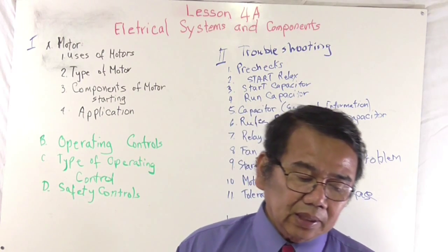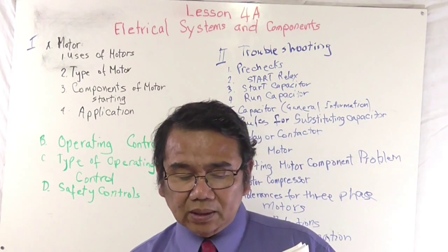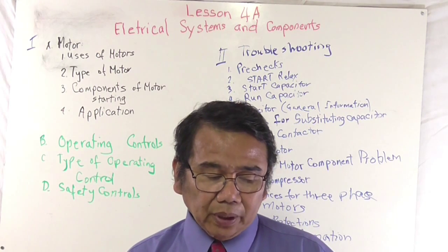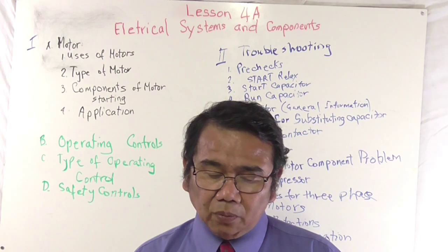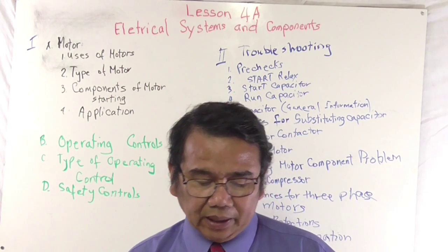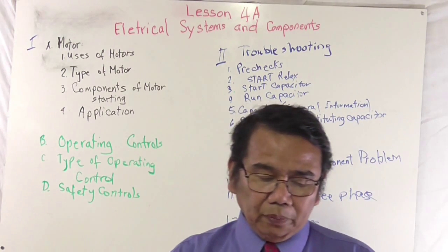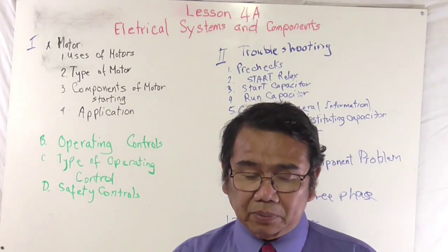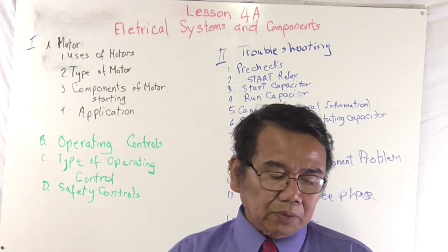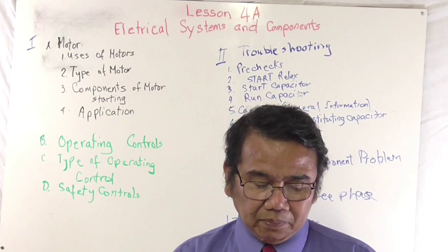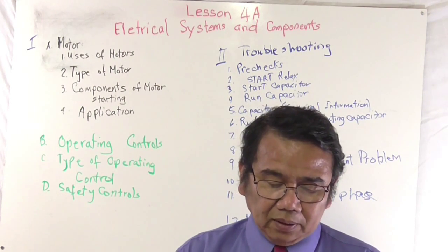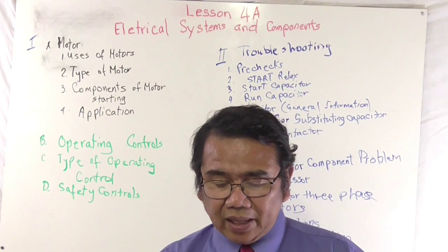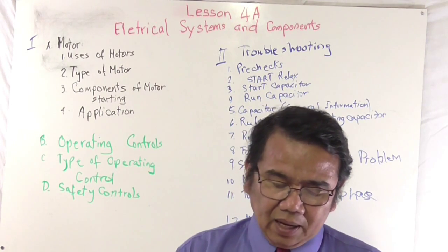If the relay is changed to one of a lower operating voltage or shorter contact operating pickup time, okay, the relay will open before 75% of full speed is achieved. The motor will stall and drop back in speed, causing rapid cycling of motor speed.